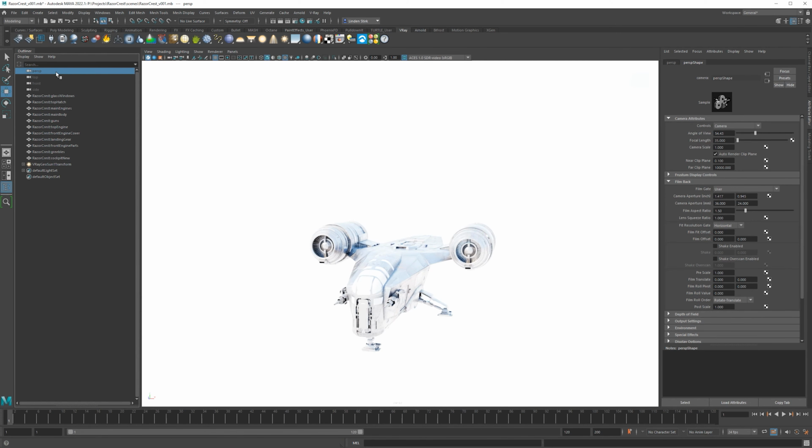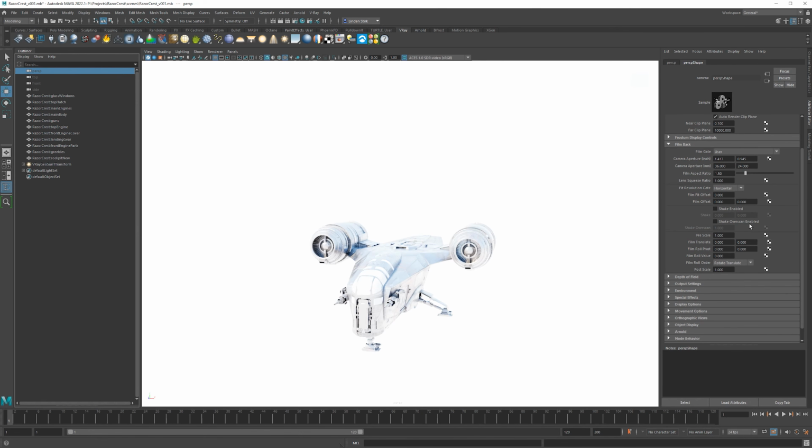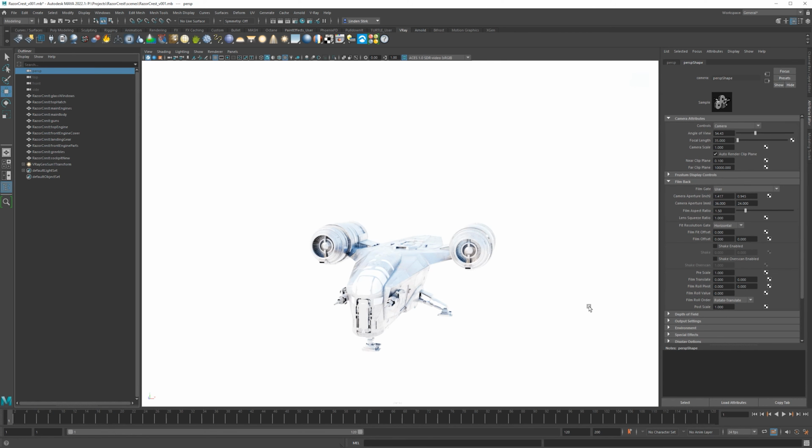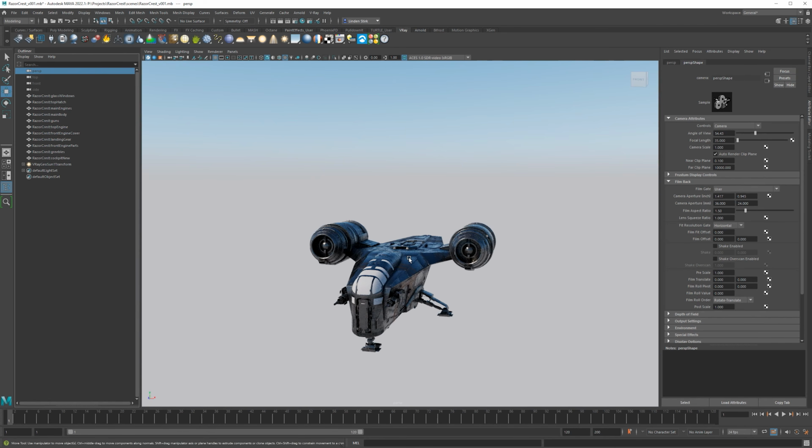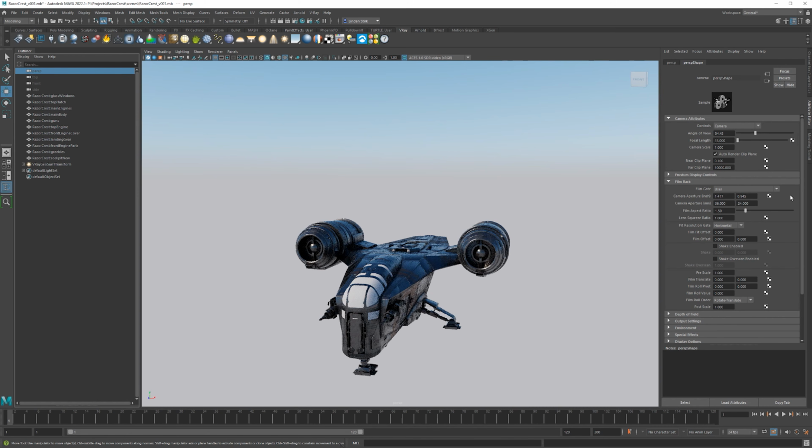I recommend that you do this on perspective and any other camera that you have, so if you render from different views, you can actually use it and it's not so blown out and unusable. The way you access the physical attributes is you go to Attributes, V-Ray, Physical Camera. When you do that, you will get a physically accurate camera and all the different things like your aperture, your ISO, all sorts of stuff.